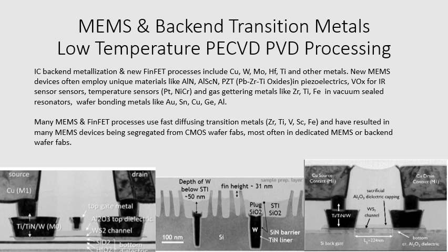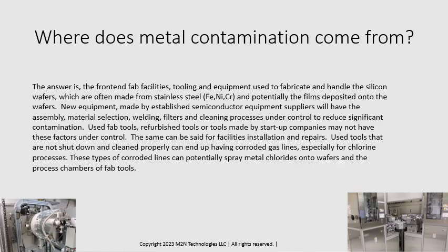Traditionally, MEMS devices are fabricated in foundries that have no CMOS or bipolar devices, so there's no worry of having these materials in active circuit devices. In the case of a typical CMOS foundry, they would be in a back-end process where the silicon wafer itself would see no high temperature after the deposition of these films.